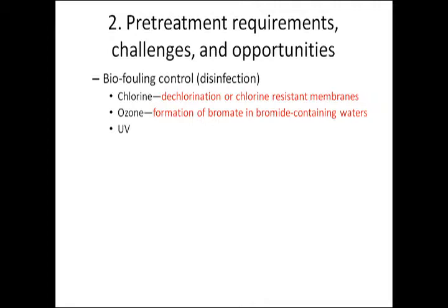Ozone is a very popular way to do disinfection, but if you have bromide in your water, you end up forming bromate, which does not get captured in RO membranes very well, and so you end up having water quality problems if this is a drinking water source.